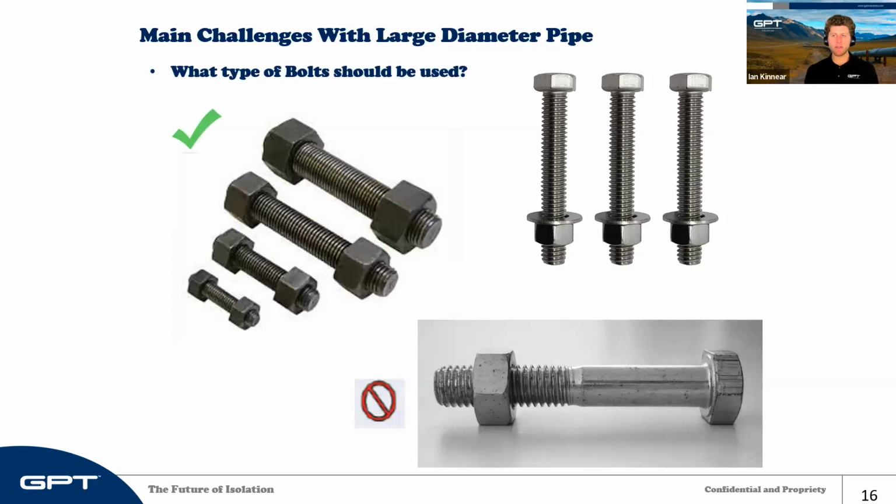And this I brought up, and it can be especially painful and expensive for these large diameters, is the correct use of bolts and studs. So the highest recommendation that we have is to use studs with 2 nuts on each side. So 2 hex head nuts like we see there on the left.